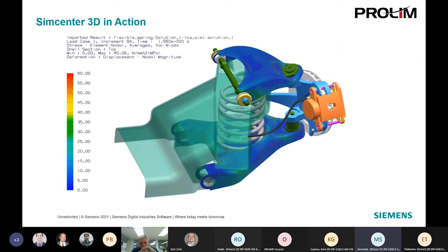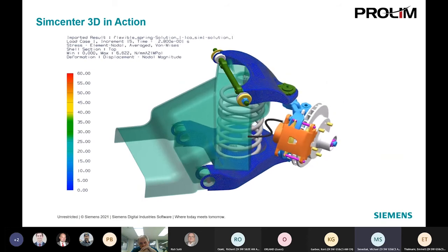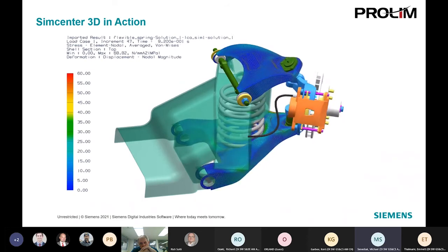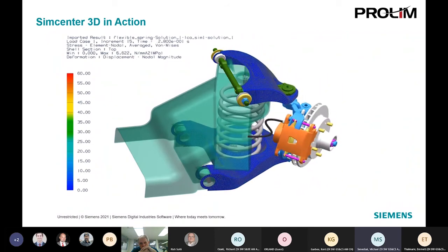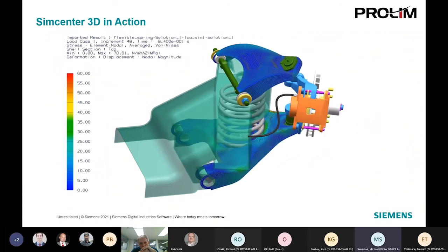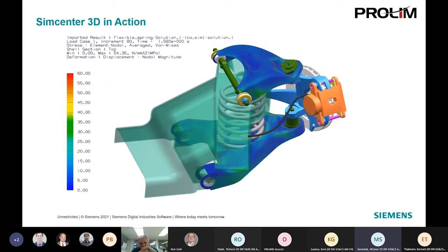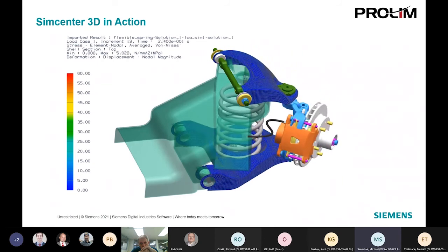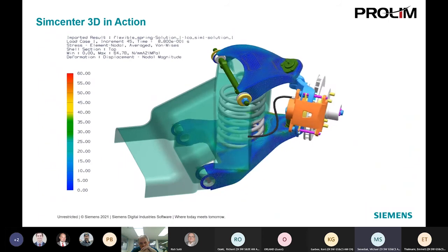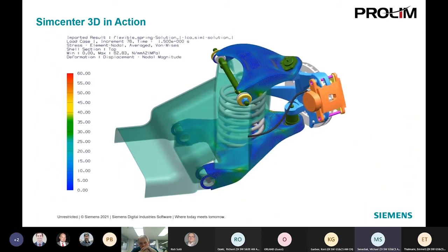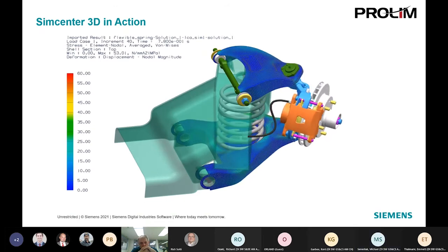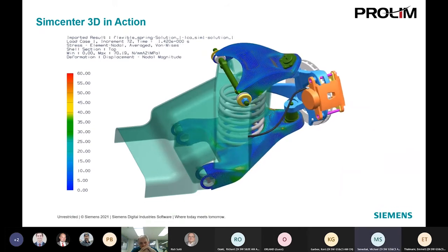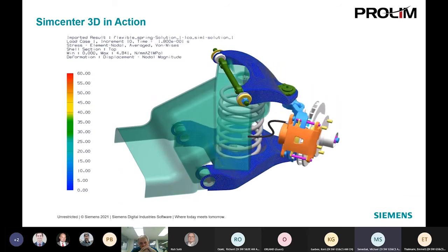You're getting a much more dynamic response to this, and really getting a chance to look at the stresses. You can see those parts. We used a 2D mesh on them. We also have some 1D elements holding it at the back, and you're seeing the impact of all of that motion and movement, which gives us a better understanding of the performance and the stresses in these particular parts.